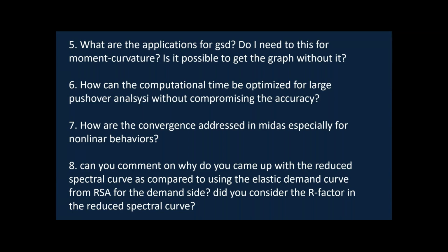Assigning this many hinges increases the computational time very much. As practicing engineers, we know that below the length of fixity of the pile, the plastic hinge won't be forming, so there is no point in assigning a plastic hinge there. This shall reduce the computational time.